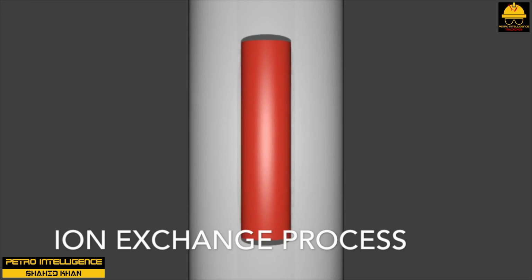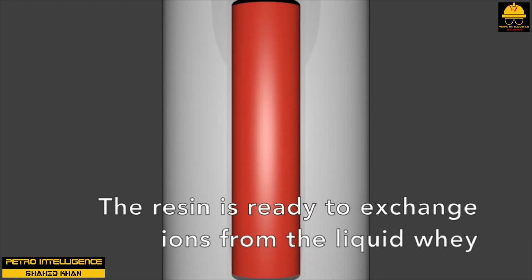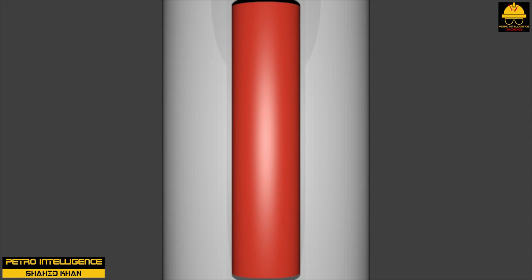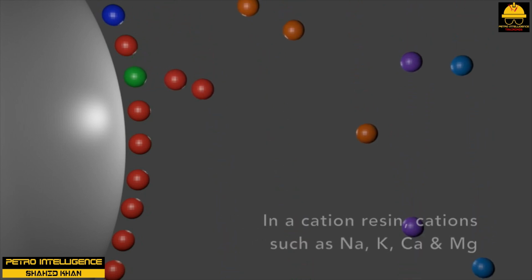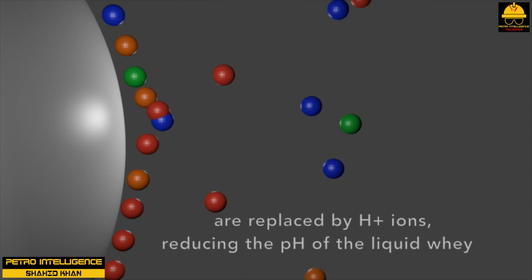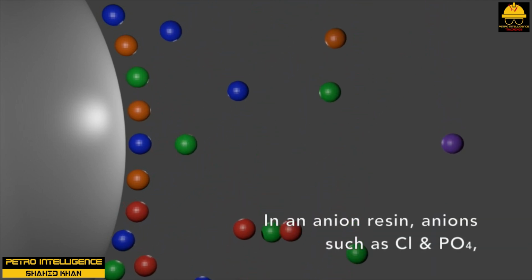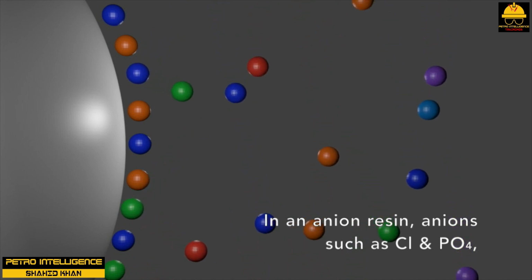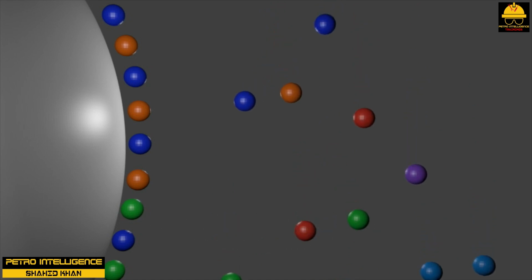Ion exchange. Ion exchange resins are very small, bead-like particles that contain charged ions on their surfaces. You will recall from your chemistry course that ions are atoms that have gained or lost electrons in their outer orbits, thereby obtaining either a positive or a negative charge. A positively charged ion is called a cation because it would be attracted to the negative electrode, the cathode, in an electromagnetic field. Similarly, negatively charged ions are called anions because they are attracted to the positive electrode, or anode.